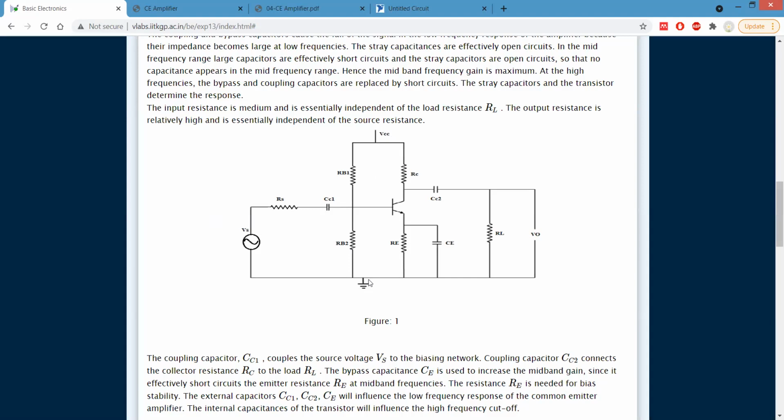From there you can conclude what kind of transistor it is. It is basically an NPN transistor, right? You have applied a positive source to the N side, the collector side. So you can directly say that the collector-base junction is in reverse bias and the emitter-base junction should be in forward bias.